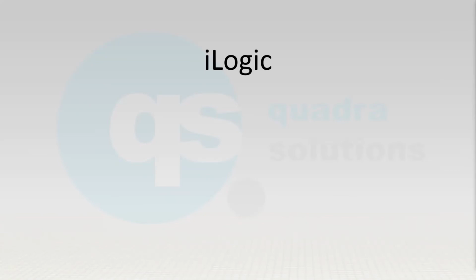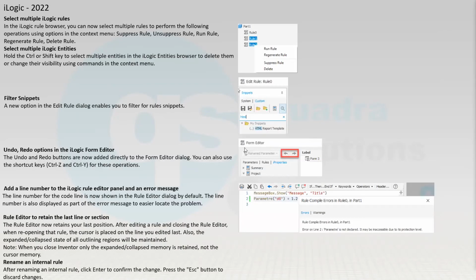We can talk about iLogic at another point. But if anybody is already using iLogic, some of the improvements, the quality of life stuff, again, nothing huge, but just makes life a lot easier. We can see that we can multi-select rules now. In the past, if you wanted to run multiple rules or delete multiple rules, you had to do them one at a time. Now we can multi-select.